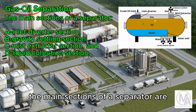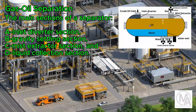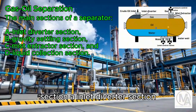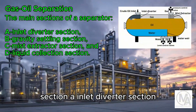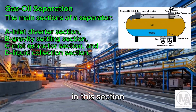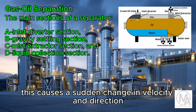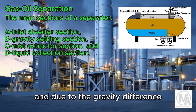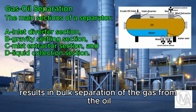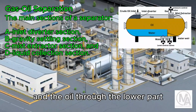The main sections of a separator are the inlet diverter section, gravity settling section, mist extractor section, and liquid collection section. Section A, inlet diverter section. Initial bulk separation of oil and gas takes place in this section. The entering fluid mixture hits the inlet diverter. This causes a sudden change in velocity and direction, and due to the gravity difference, results in bulk separation of the gas from the oil. The gas then flows through the top part of the separator and the oil through the lower part.